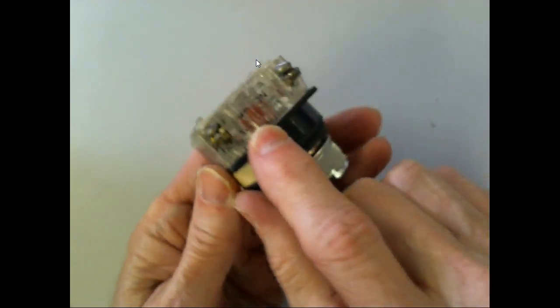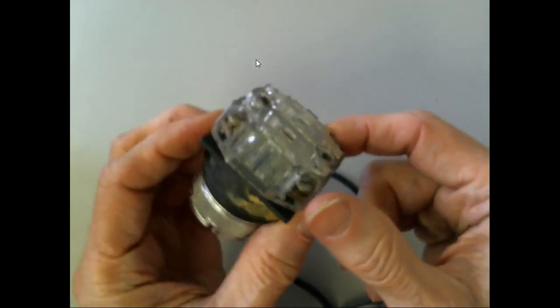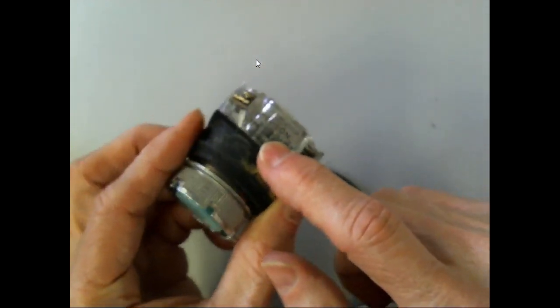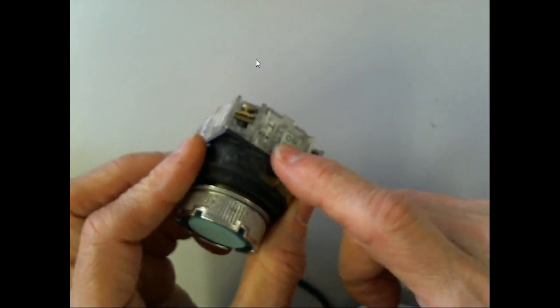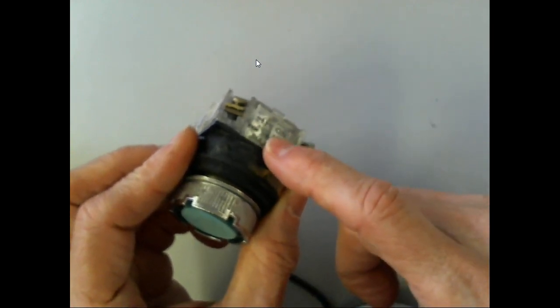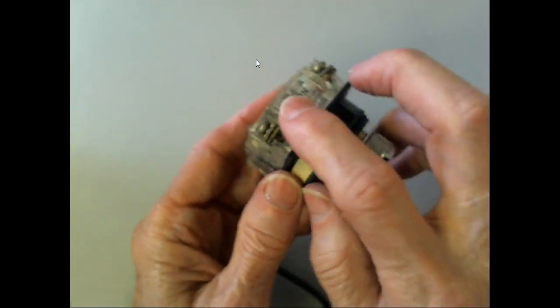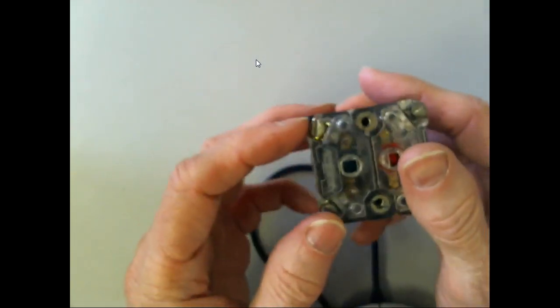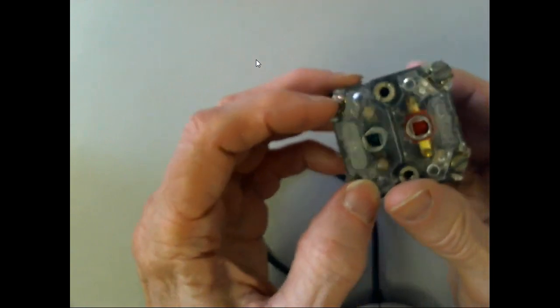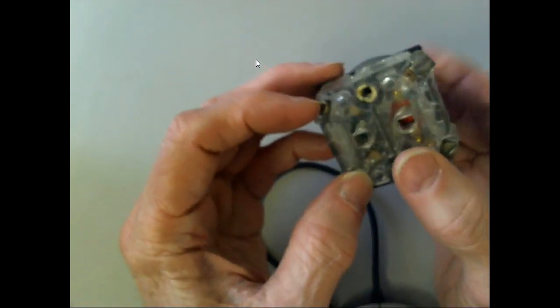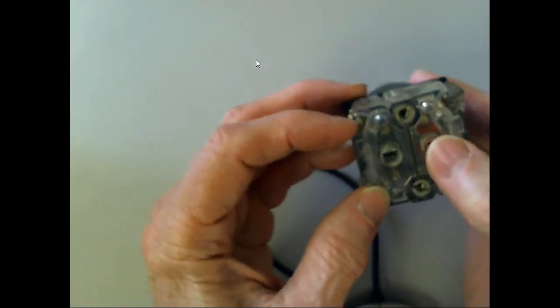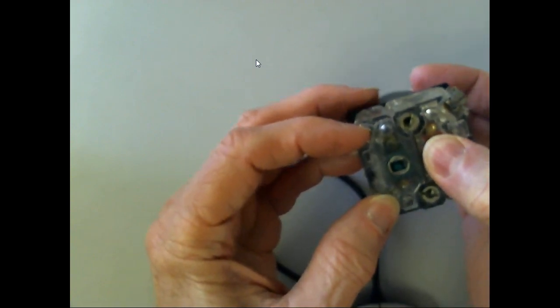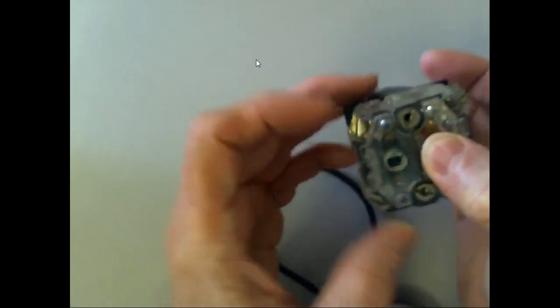And so this gives us a normally closed contact. The normally closed contact is on this side, and a normally open contact is on that one. What this does is actually put the symbol on there for you, right? So there's the symbol for the contact, and this shows this is normally closed. If I was to take an ohm meter and put it across here, right now the ohm meter would measure infinity or overload, and then when you push it, it should go to 0, right? You understand? That's the normally open one.